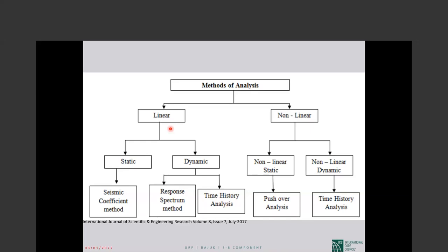Now we have the demands for those control actions, and capacity is simple for force control, for the scary ones, for brittle ones. For them, we just look at their strength. We don't want to check their plastic behavior, for example, because we don't want them to go through that range of behavior. If they pass the strength limit, then they are gone.